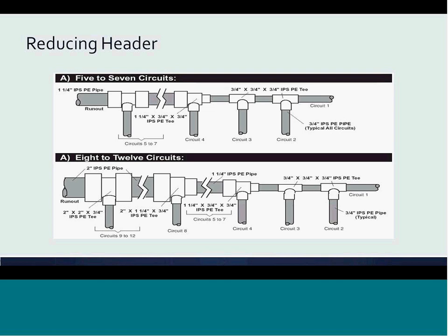Connecting a few loops together for a residential system or hundreds of loops together for a school, it is important to think about how all the loops should be connected or headed into a main pipe for pumping to the heat pumps inside the building. A header is recommended to gradually increase or decrease the system pipe size to match the system flow rate. In some cases, these headers can be purchased prefabricated for closed head applications. Usually, these reducing headers are fused in the trenches.